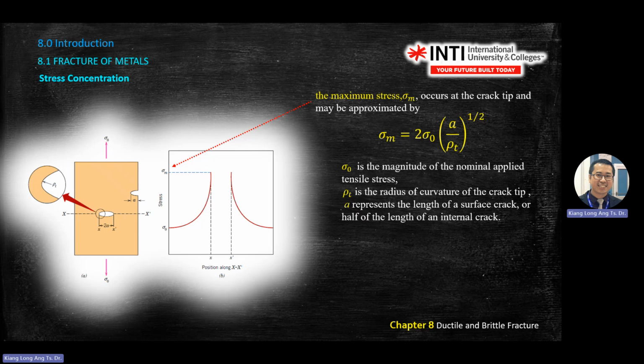So you see the X and X0, so X0 here. Here you see the other side is also from maximum to a normal nominal stress. In the previous mechanics chapter, we were using nominal stress, the one that you calculate in your test. Here, the value will be higher than the nominal.